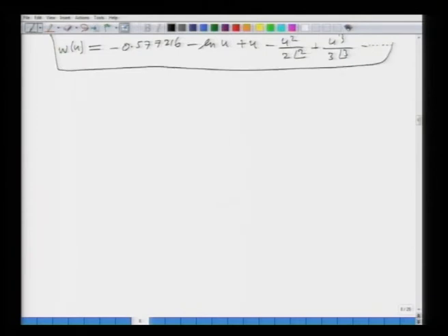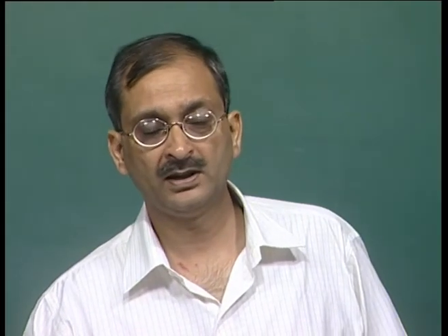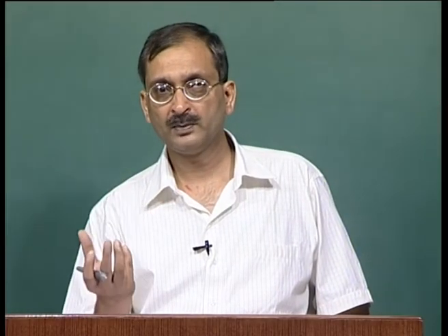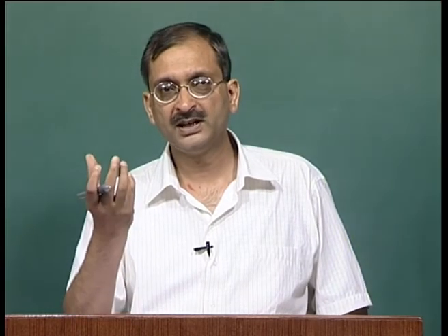Okay. Now, as I said earlier, this non-equilibrium equation is something which is applicable under the unsteady state condition, when things are changing as a function of time. When you start pumping, the cone of influence or the cone of depression will be forming, which will be changing as a function of time.